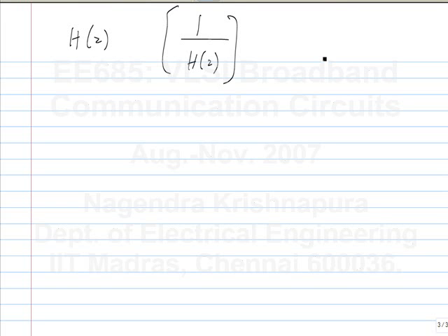Meaning, then the eye is not open. The eye is not open. That is strange. Okay, one thing I realized also is that the best thing in this particular case, in the low bandwidth case, you need to have 2 precursor taps. But the way I framed the problem, I have constrained you to 1 precursor tap. It will still equalize it. From my simulations, it looks like it will equalize it.